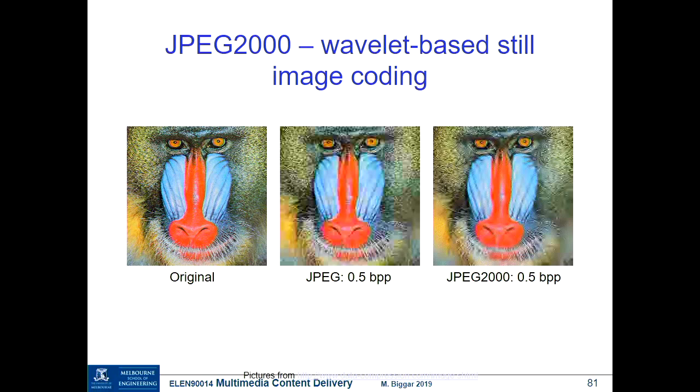Or is the question not clear? Probably the question is not very clear. We're trying to reduce the bit rate a lot for JPEG. The quantization step or quantization interval is very large. So only the largest coefficients will be preserved, and the largest coefficients will be, which ones? Will be the very low frequency ones.